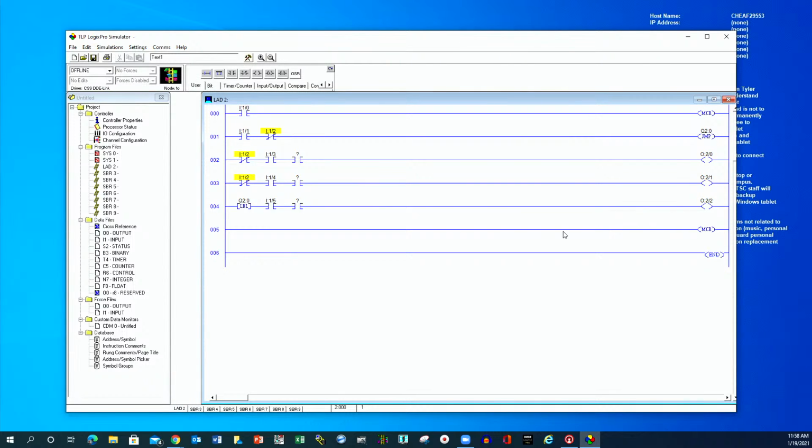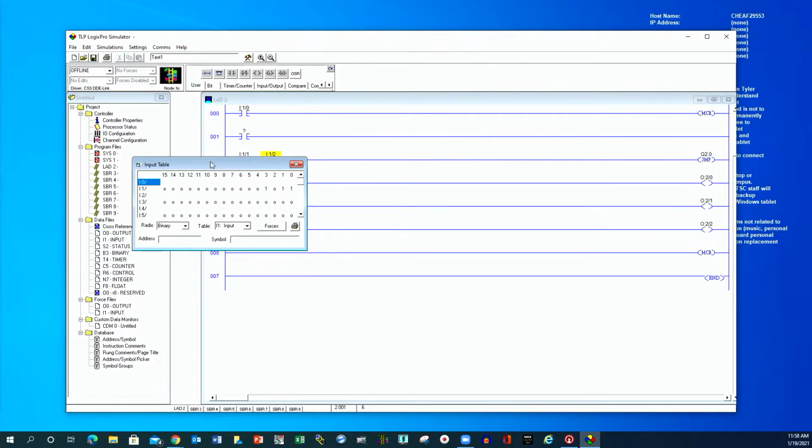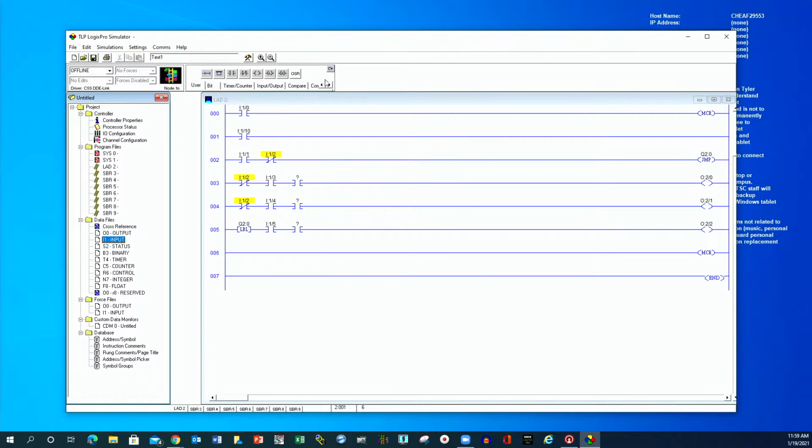But we have to be able to leave and go down to the subroutine. So let me go here. Let me put it right here. I'm going to add a rung, and I'm going to make it conditional. I'm trying to add all these things on one program so you kind of see how they all work together. That's the purpose of this whole thing. All right, so I'm going to put a condition here. I'm going to grab one that is not being used currently. Let's use 10. So when input 10 is made, I'm going to jump to subroutine.